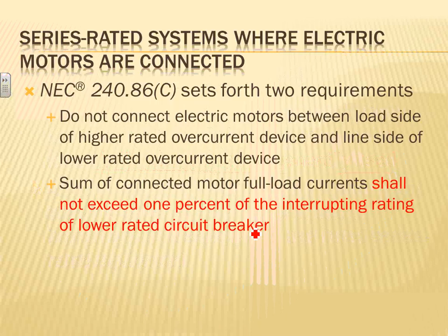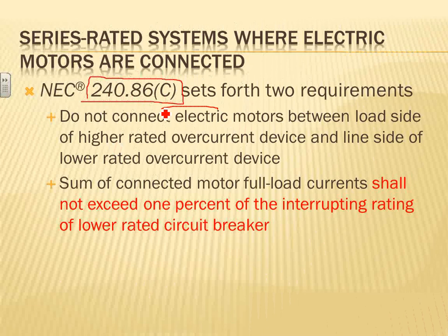Okay, so that's this one. Here's a couple of things. If you have series rated, the NEC code book requires two requirements to use a series rated. Number 1, do not connect any electrical motors between the load side of the higher rated overcurrent protection device and the line side of the lower rated devices.